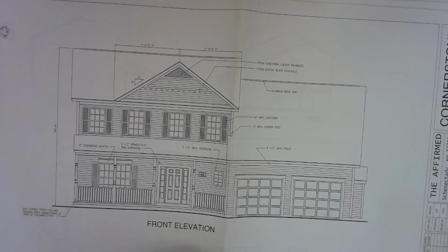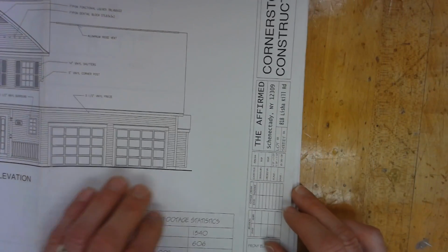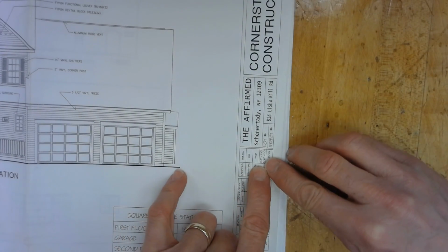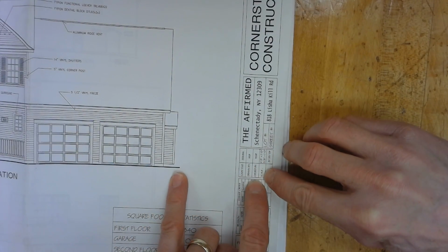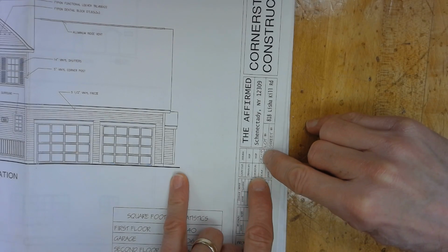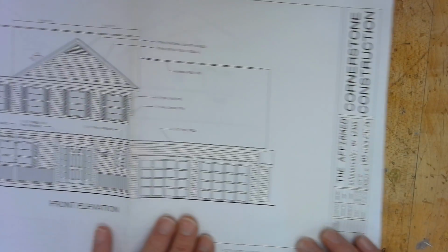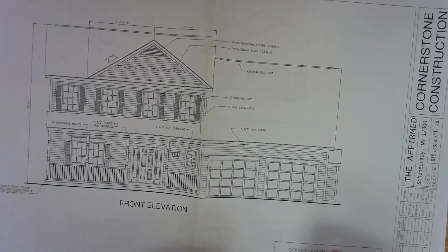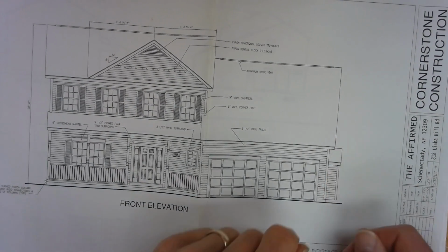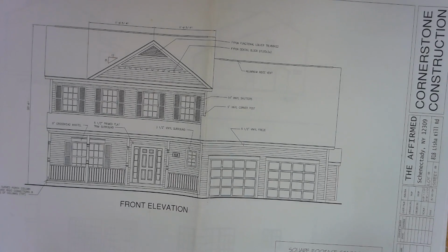Okay, and scale. And if I could show you this, I'm not sure if you're going to be able to read that or not. It says right there, scale. The scale is 1/8 of an inch equals a foot. So what they're telling you, if you measured 1/8 of an inch on this right here, if we took a ruler and measured that, well, when you go to build it, that's really supposed to be a foot. So 1/8 of an inch equals a foot.